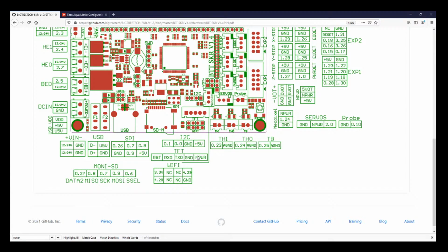Let's take this out of the way and look at the board again and see what the actual tracings say. So if I turn this up and I look at it, looks like we're looking at the TX, and 5 volts is on the very right hand side. So if we trace out the cables here, we see that there's a dash all the way up that goes into here. But over here, we see a dash on the far left-hand side for TX. So there might be something going on with our cable. So let's try a different cable.